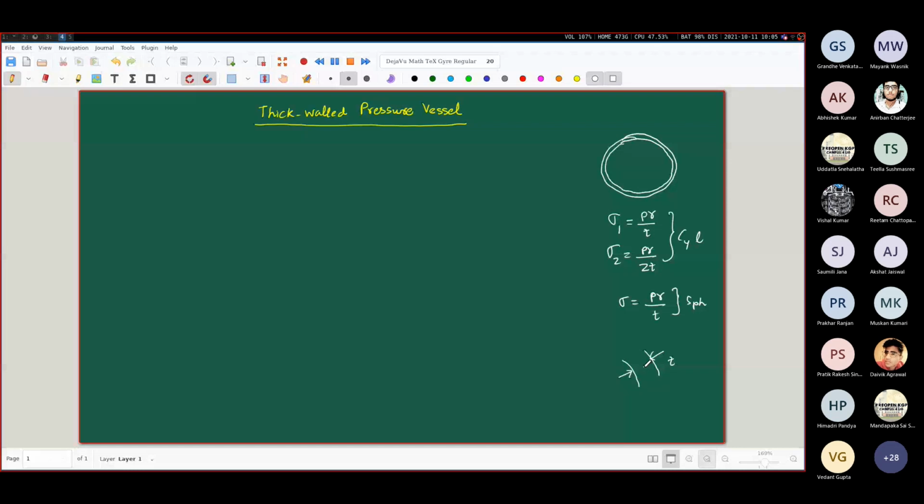That is important because the condition which the thin wall is experiencing at the inner radius is the influence of the pressure from the inside, the gauge pressure. And on the outside, you can either think of it as the zero pressure if you're considering this as the gauge pressure, or if you're considering this as the absolute pressure, you can think of this as the atmospheric pressure.